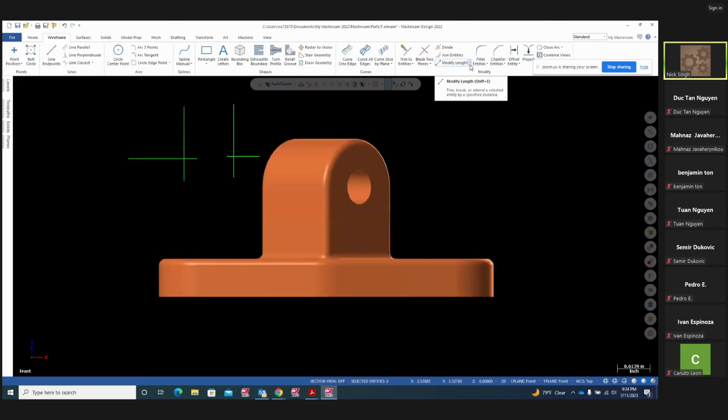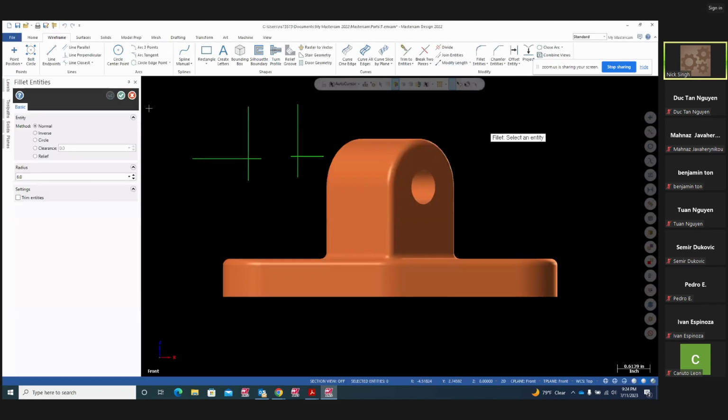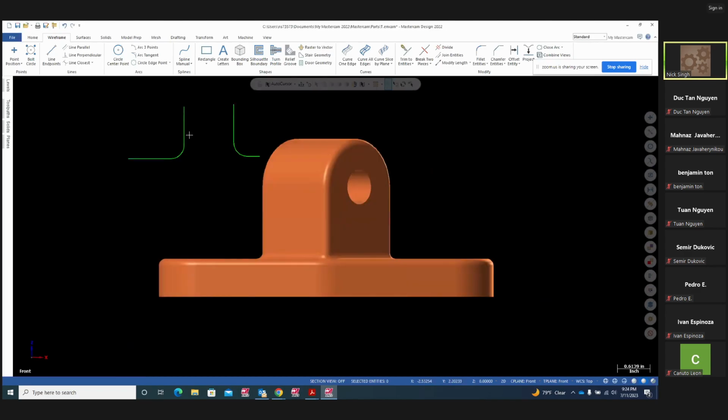So if I'm going to make a fillet entity, radius, let's say 0.1, here let's make it 0.250 so you can see it. Trim it. And there. So here, my fillet is cutting inside. So in this case, if that's my surface, my normal has to be in because the center of the fillet is right here. So normal has to be in.